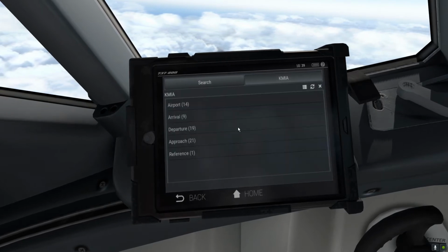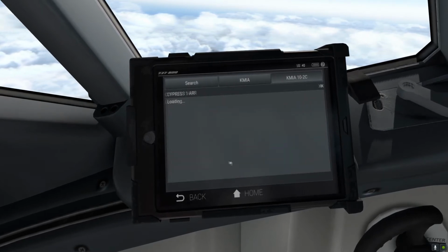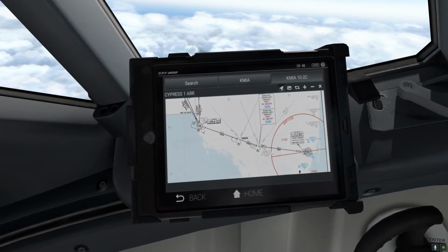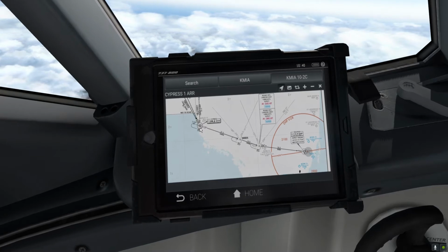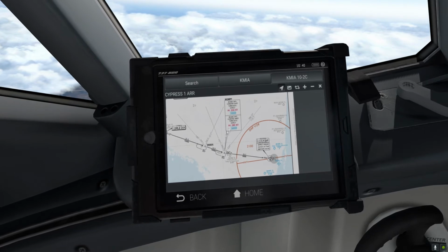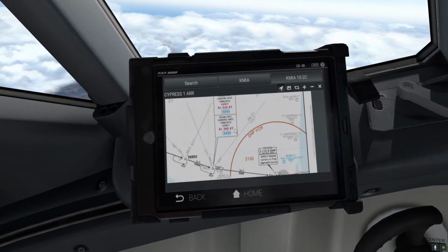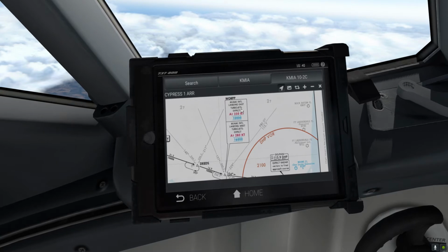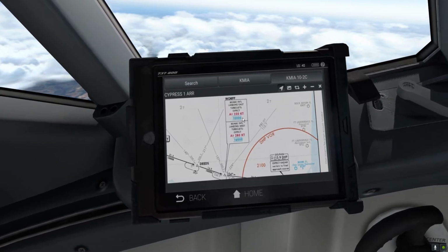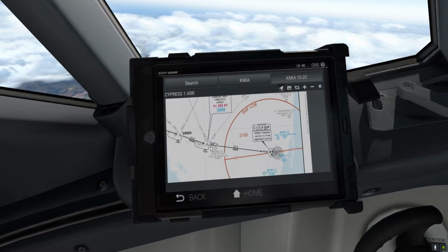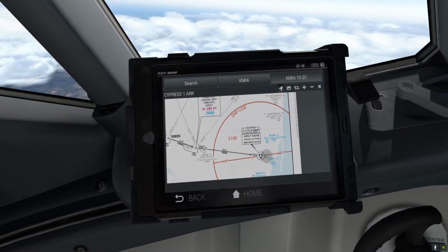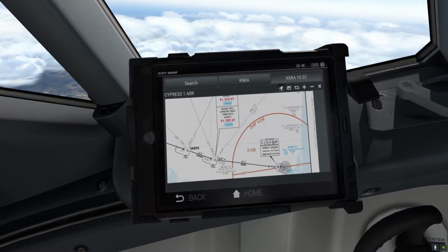Anyway, our arrival is going to be the Cyprus 1 arrival, flying direct Cyprus VOR, and then we're gonna fly to Deeds and to Warp with this kind of limitation. We have Miami International landing east, turbojet, expect 10,000 feet and 250 knots by this point, and then we're gonna fly to Dolphin VOR, but of course we expect radar vectors before Dolphin